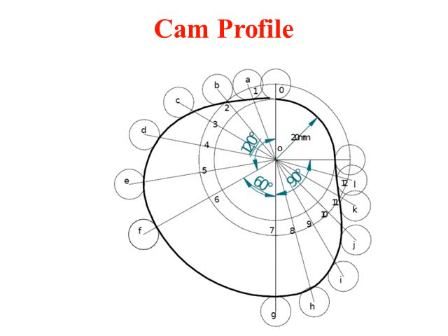So first draw the base circle with O as the center. Next, again with O as the center, we need to draw the prime circle, and the radius of the prime circle will be the radius of the base circle, that is 20 mm, plus the radius of the roller, that is 5 mm, that will be 25 mm. So again with O as the center, draw one more circle of radius 25 mm. That will be the prime circle.